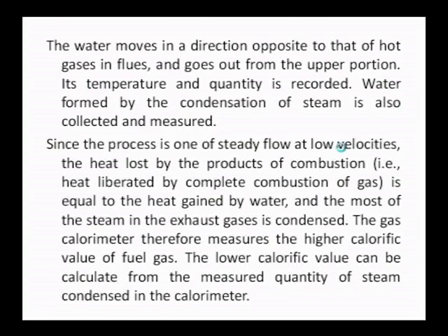The gas calorimeter therefore measures the higher calorific value of gas. The lower calorific value can be calculated from the measured quantity of steam condensed in the calorimeter. That means after calculating the higher calorific value, you have to subtract the amount of heat lost to the steam. When you subtract these two, you will get the lower calorific value.